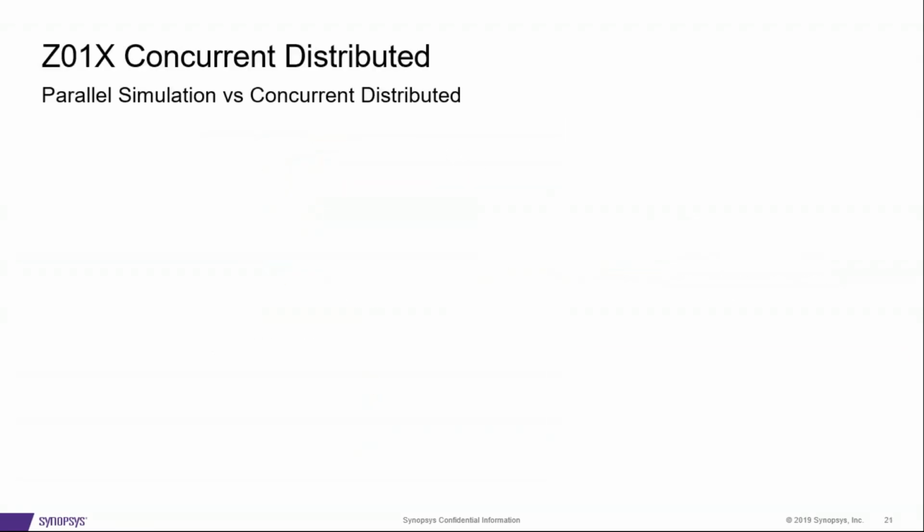Now, if you were to do this as part of a simulation process, and most likely you have to for things like ASIL-C and ASIL-D, bear in mind that you're dealing with a fairly large problem in terms of computation resources. Say you've got a 250K gate design, and you're looking at permanent faults, stuck-at-1 and stuck-at-0. Very easily, you're going to be looking at 500,000 faults, maybe up to 1 million faults. Doing this by hand, going to a simulator like VCS and forcing a node to 0, forcing a node to 1, you very quickly need a large infrastructure.